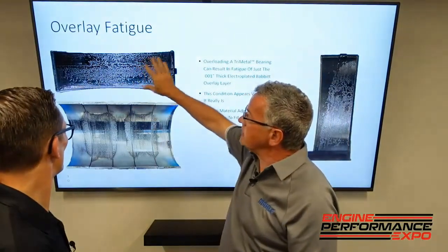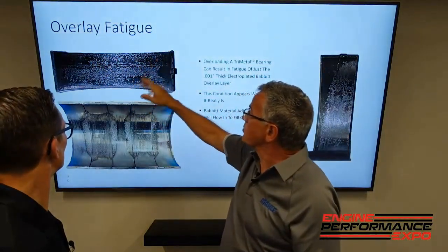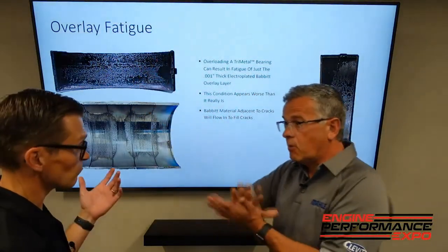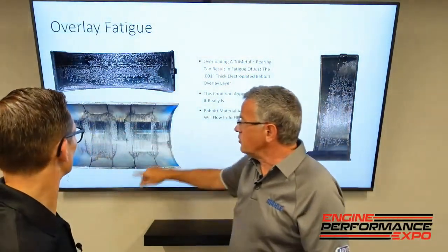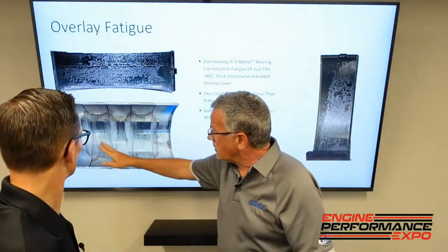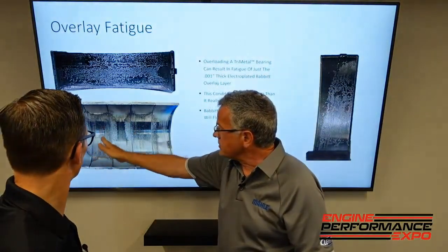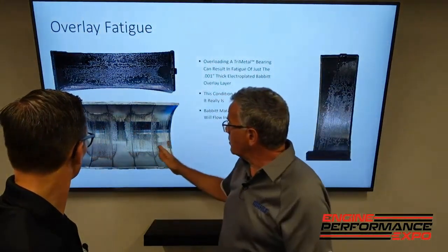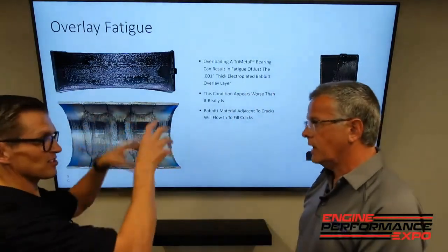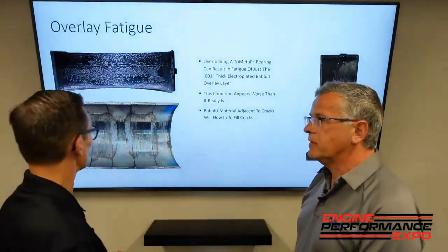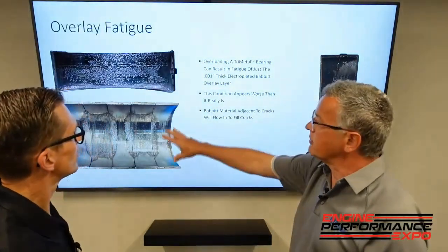Typically, when you see something like this, that could be a connecting rod bearing where it's just that amount of cylinder pressure firing in there, moving it. This is crank flex moving around, and you're seeing it wearing. Ironically, it's a lot of flex going on here, front, rear. You can see those areas where it's moving, just like you said. That's really clear. That's crank flex going on, causing fatigue.